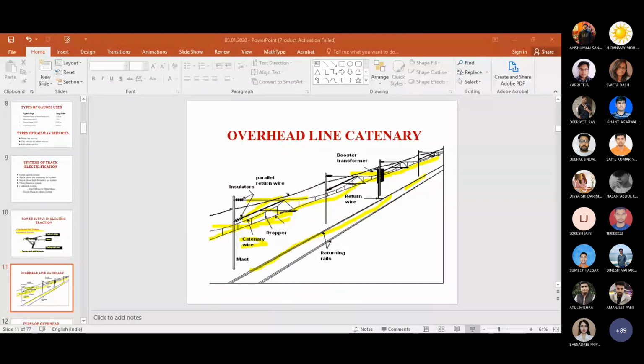If it is 230 volts and the resistance is 0.5 ohm, how much current will there be? V equals I into R, so 230 volts divided by 0.5 comes to more or less 460 ampere. So 460 ampere flows directly through your armature winding of the DC series motor, whose armature resistance is not high.